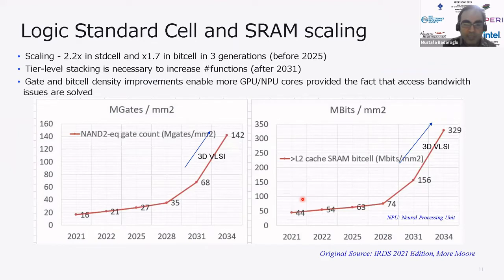If you look at the perspective of how the device scaling, how do we get the area scaling? So until 2028, DTCO can still help, particularly for the logic device improvement. DTCO is reasonably okay. But on the SRAM side, there is a relatively flattening curve, and then the only pickup possible for both logic device and the SRAM is by 3D stacking, logic and logic scaling.